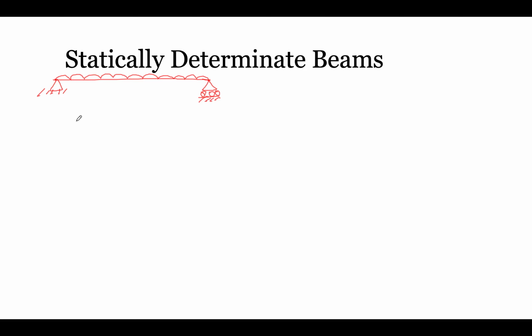For this particular beam, when we have to calculate reactions, let us call it beam A and B. For the above beam, let us calculate reactions first: summation of forces in x direction is equal to 0, summation of forces in y direction is equal to 0, and summation of moment equals to 0. So we are going to solve this particular question.